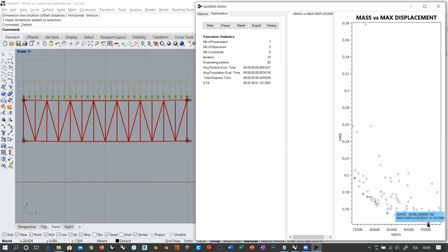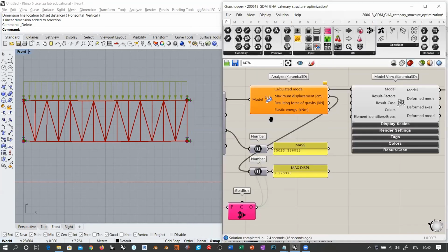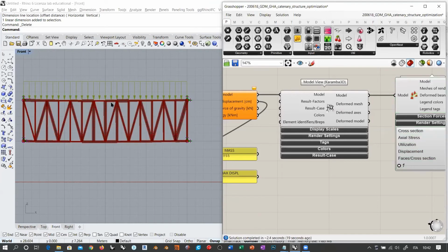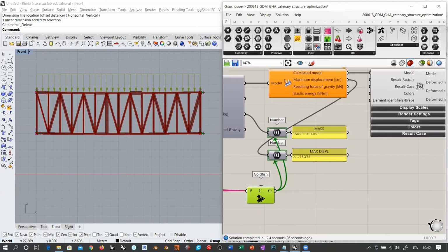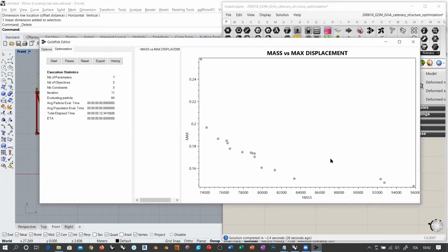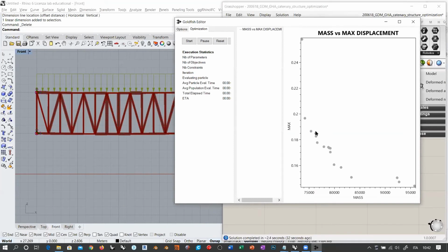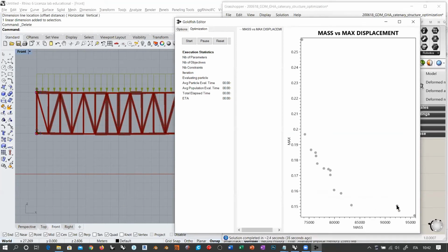So I think we got already to less than 0.15 centimeters. You see that we still add dots in this area, even if we have this one. It's still adding dots in this area because these are more optimized, because they are also optimizing the mass of the truss. Okay, so for example, let's pause this forever. Let's reactivate the mesh representation. Of course, this is a somewhat messy representation because I don't know at what iteration I stopped the optimization, but this is the last iteration. And it doesn't mean that you have a better solution, right?